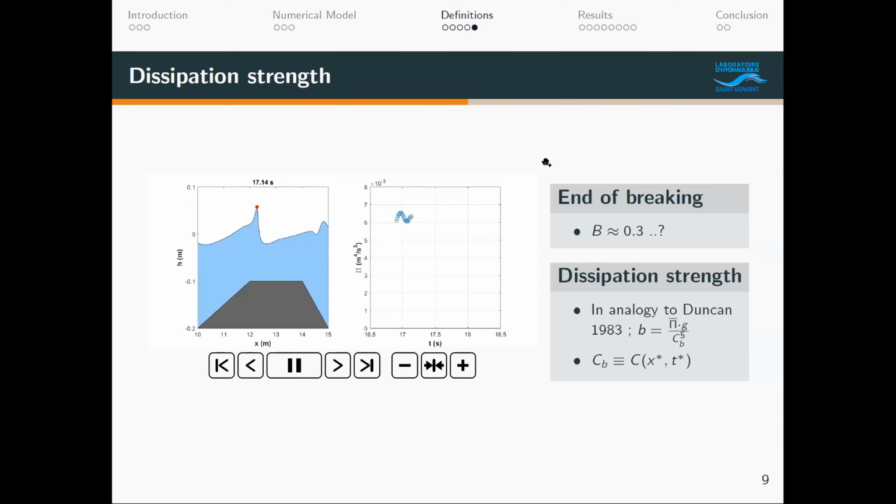And then wave breaking is turned off at 0.3, and there isn't much information about this, and we iteratively selected this by comparing simulation data with a few experiments in the region far ahead of the breaking waves, and we will look at that when we look at results.